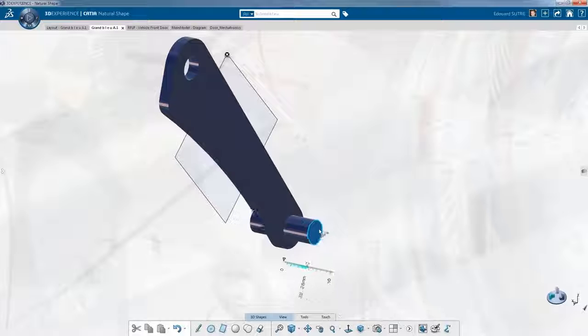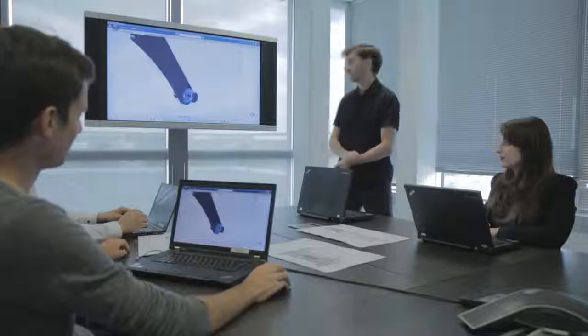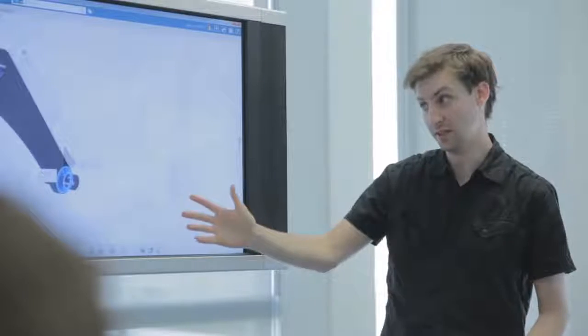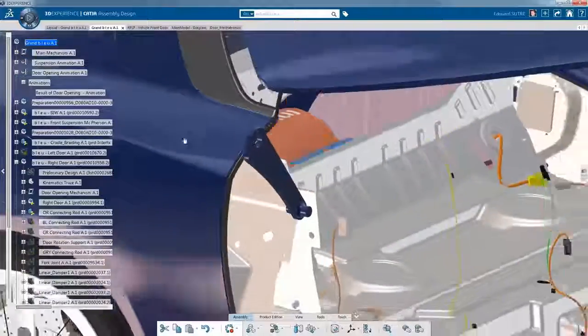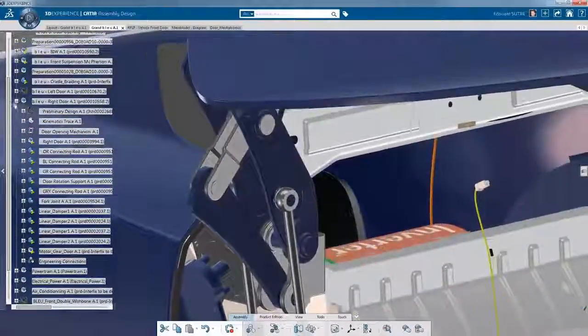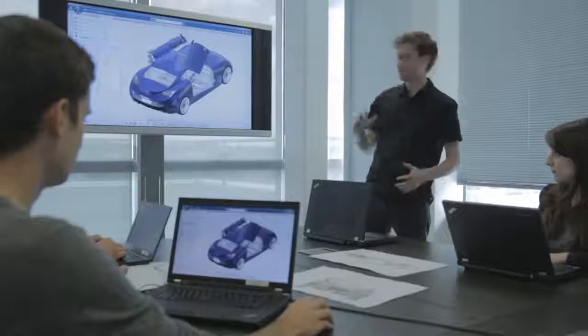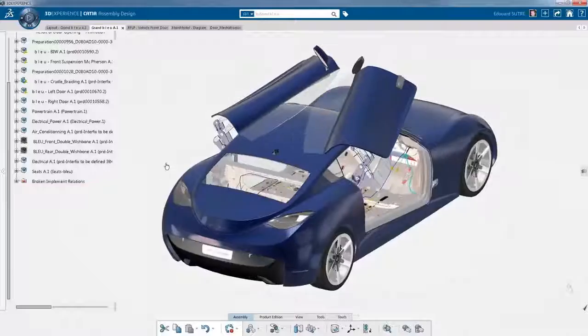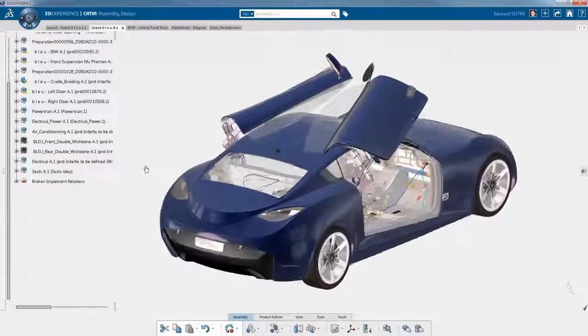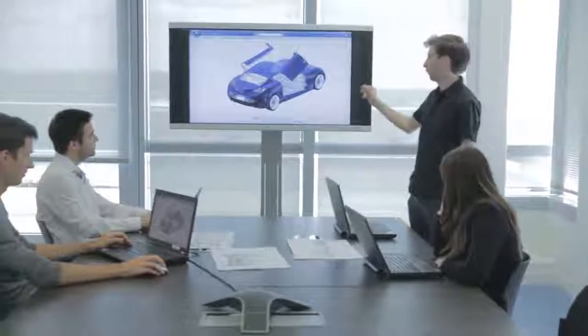This concept phase rapidly gives them the capacity to propose some alternatives without entering in detailed design. But all of that, as you can see, is directly designed in the context of the complete car program definition. So they were able here to manipulate, create all single parts, and create this mechanism. Based on this mechanism, now they want to simulate the first level of kinematics. So for this simulation, they just have to select the play button of the compass where all of the constraints of the assembly are directly reused for simulating the first level of kinematics movement.